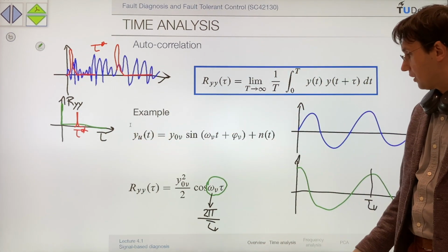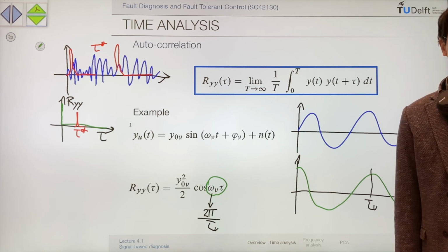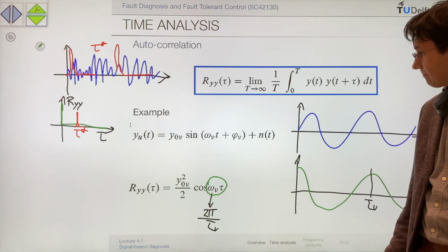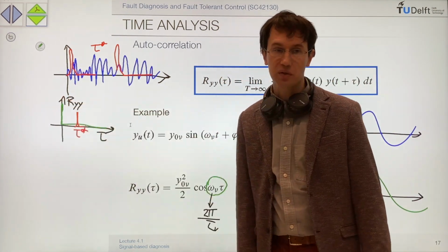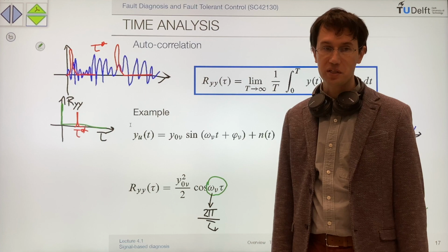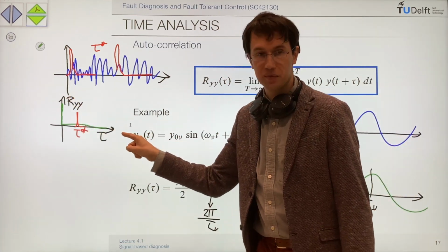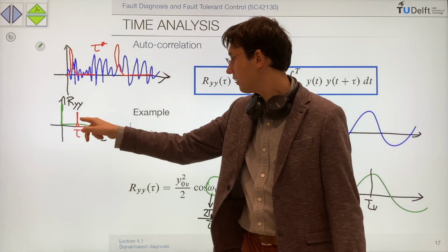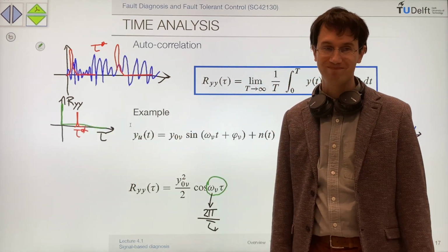Anyway, once you have your autocorrelation signal, you can derive a threshold that is big around 0, because you know that around 0 your signal is always correlated, but is small for other values, such that when you have a peak, a red peak like this one, it is crossing the threshold.